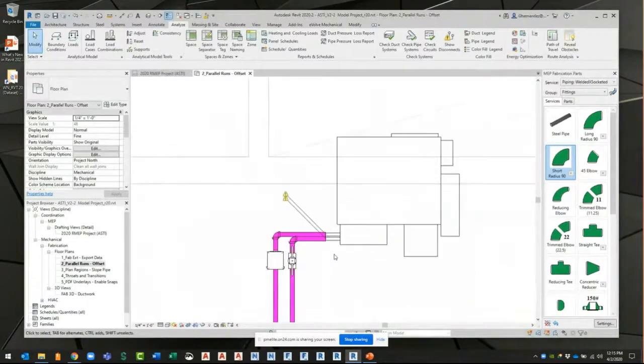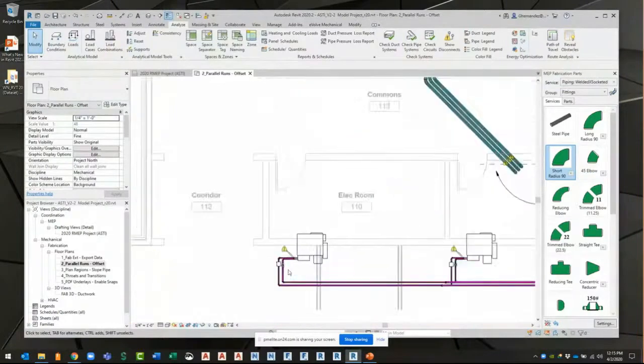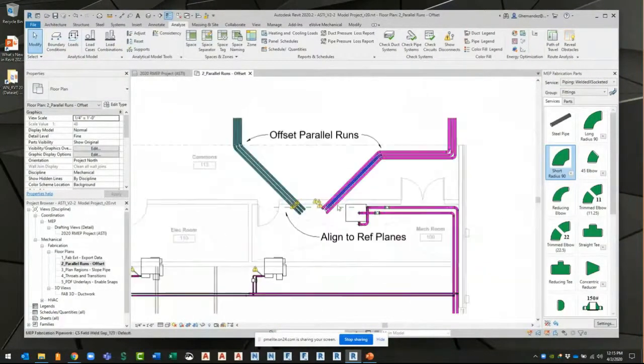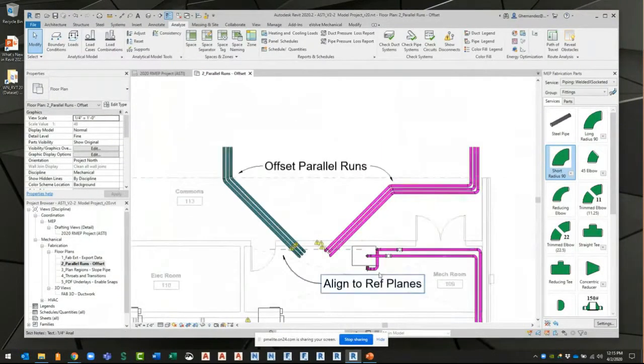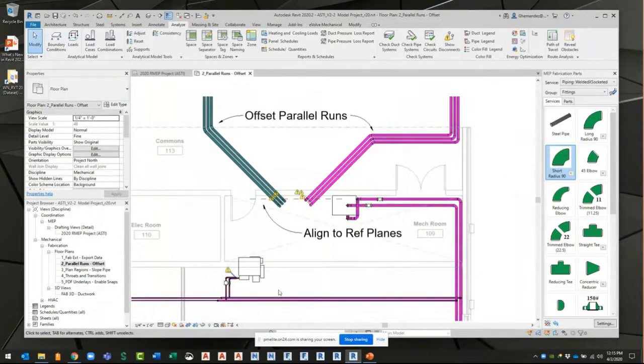So I've got disconnects over here. I've got disconnects over here. And I've got disconnects over here, of course, which I already knew. But this kind of shows you the integrity of the model. Before you do a convert or design to fab, you would turn that on to see what the Revit model looks like, if it's well connected. If it's not, you do your best to reconnect where you can and then design to fab, and that will give you a lot better conversion as well. So it's a little bit extra work, but it's a good place to check things, right?